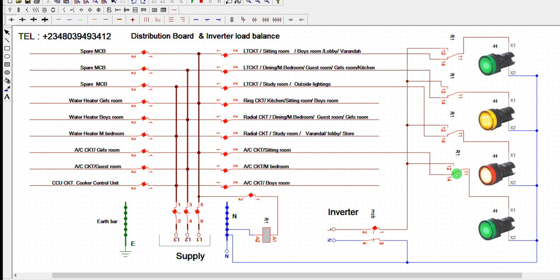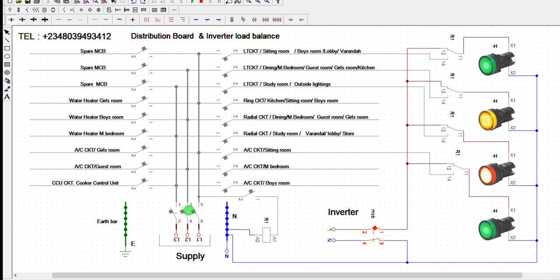The relay, I've cut it off. So I'm using my normal supply, be it standby or coming from the national grid, at my circuit here. It's not coming from the inverter. So my inverter will now concentrate on charging the battery. But when my national grid or my genset is cut off, that is when my inverter gives me output through my battery inverted energy.